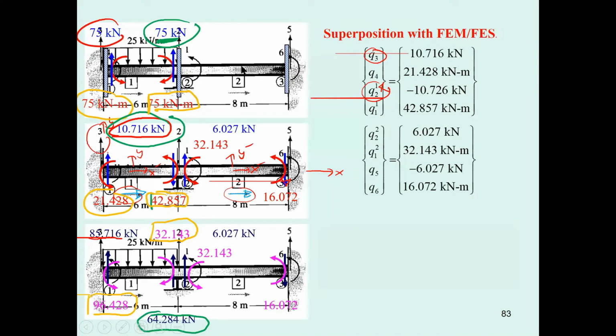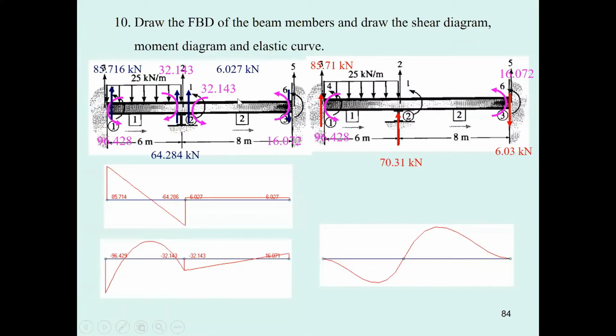So that is going to be your work, and then you have to use your free body diagram, draw your shear diagram, draw your moment diagram, and then by doing this, you know, this is going to be what? Going to be the inflection point. Before that, we didn't check the inflection point for this.